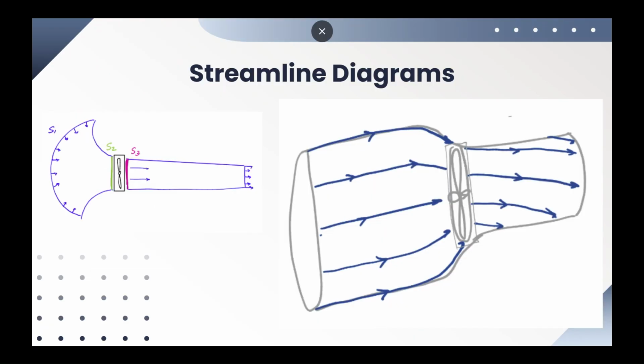From our geometric measurements of the airfoils and measurements of the wind speed before and after the fan, we understand the box fan as a system that draws in air from the ambient room and creates a speed and pressure difference through the rotation of its airfoils. In addition to higher wind speeds after the propellers, an azimuthal rotation rate defined by an angular induction factor also creates a twisting of streamlines after the fan.